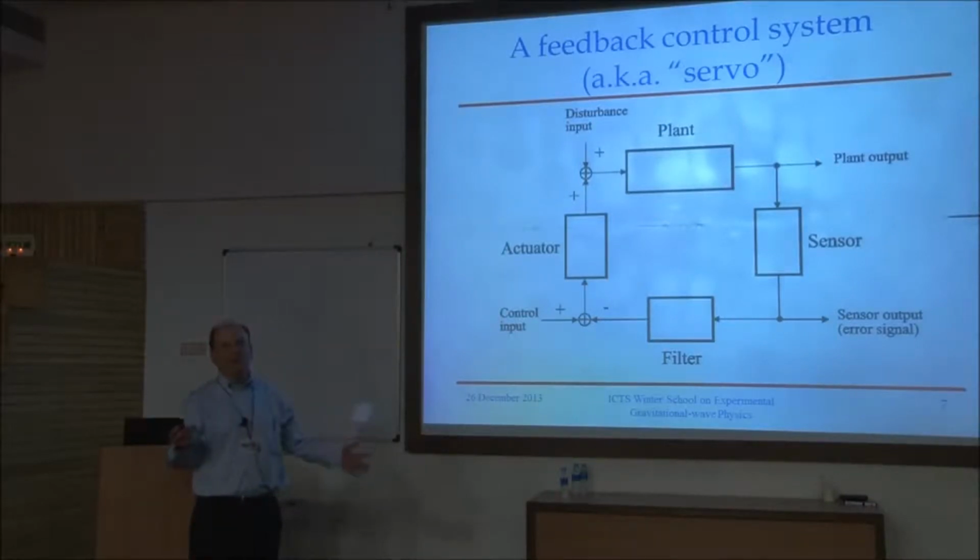So let's imagine we've got something, and this may be an arm, it may be a whole interferometer, it may be some platform of masses and springs that we want to turn into a good low-frequency vibration isolation system. And every time I draw a box here, I'm thinking of something that has an input and an output. And also, these are things that are connected to each other in such a way that, unlike the stack of mechanical stages in a passive vibration isolation system, we can, in almost all cases, and I think in every case that I'll be discussing, treat things as if there's no back action from something downstream.